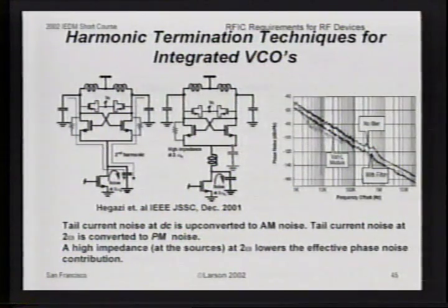And the very simple explanation for what's going on, but the performance improvement is quite dramatic. With no filter and with the filter, there's maybe an 8 to 10 dB improvement in phase noise. So what that does is it allows you to build a VCO, a non-chip VCO, whose fundamental performance limit is limited by the quality factor of the tank circuit and the noise factor of the transistors itself, which ultimately is what we're trying to do with these circuits: get to the point where we're limited by fundamental physical processes and not by extraneous biasing issues.